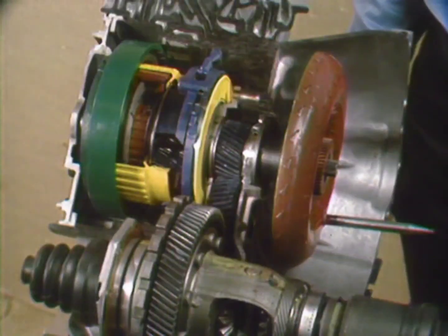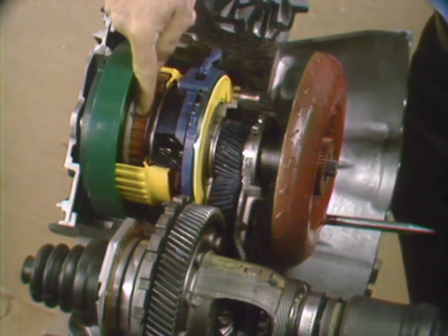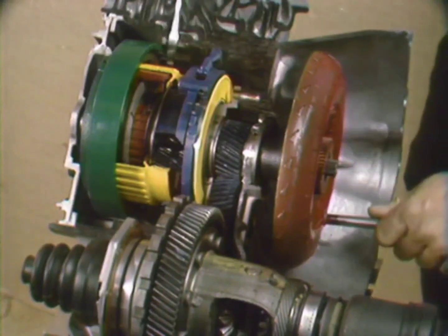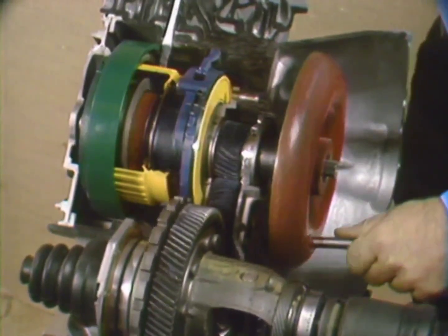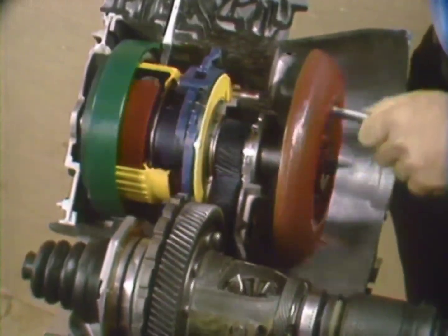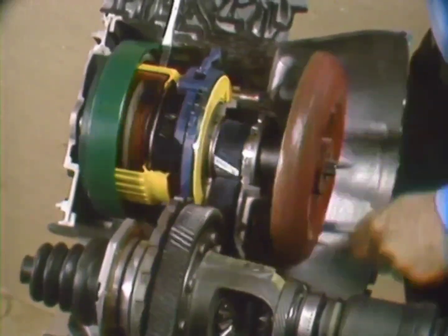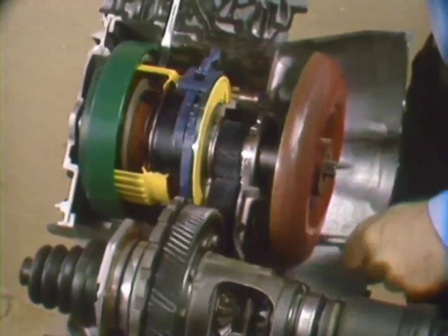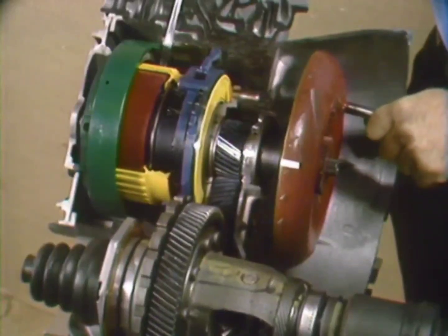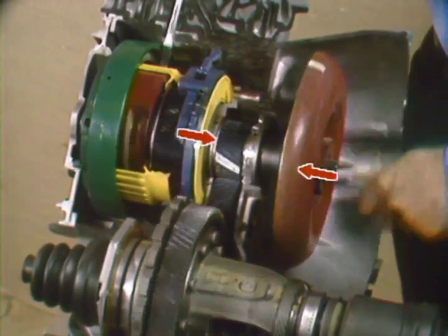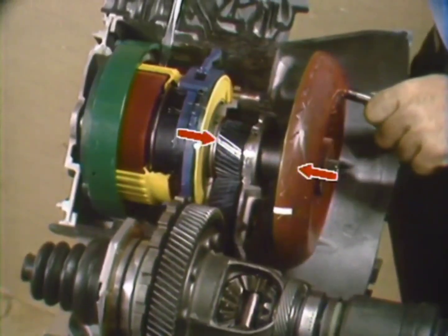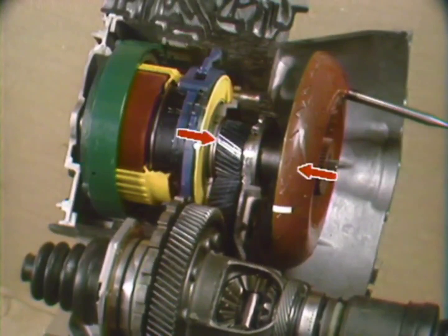Now, Joe has set up the cutaway for reverse gear. The direct clutch is applied. The ring gear is held stationary by the reverse clutch, so he'll hold it as he turns the turbine and turbine shaft. Watch the action. The turbine, splitter sun gear, and turbine shaft are all turning clockwise, but the planetary carrier and final drive input gear are turning counterclockwise. Watch the marks and the gear reduction of 2 to 1. 1 turn of the final drive input gear takes almost 2 turns of the turbine.